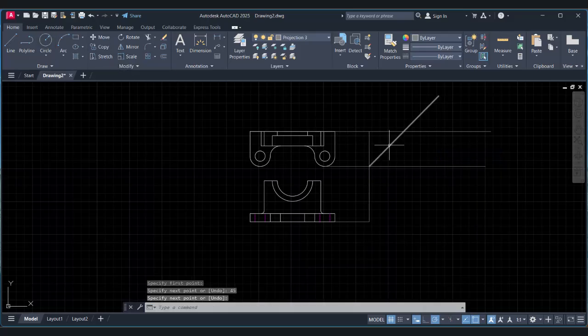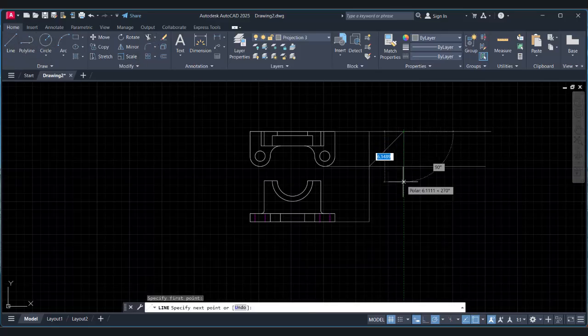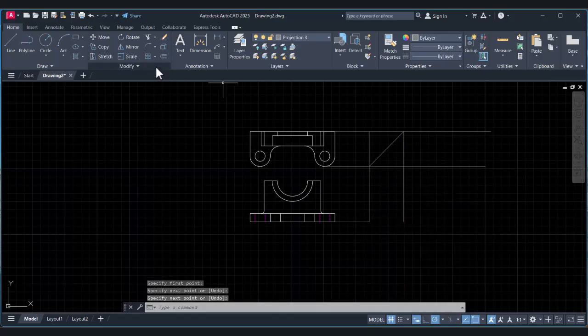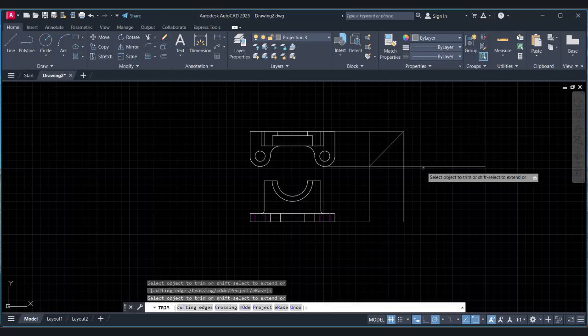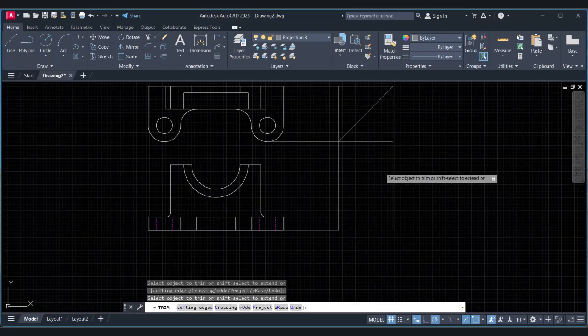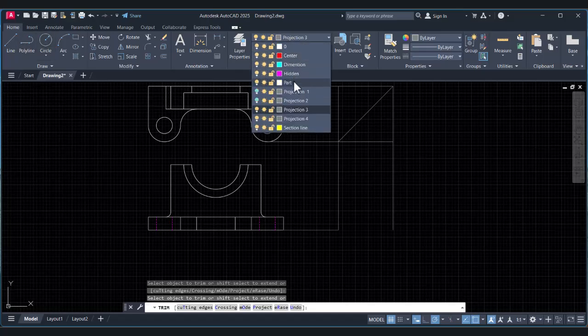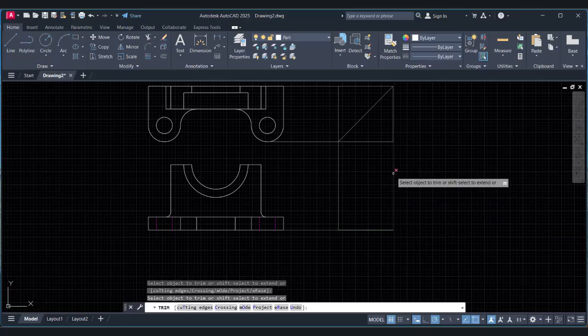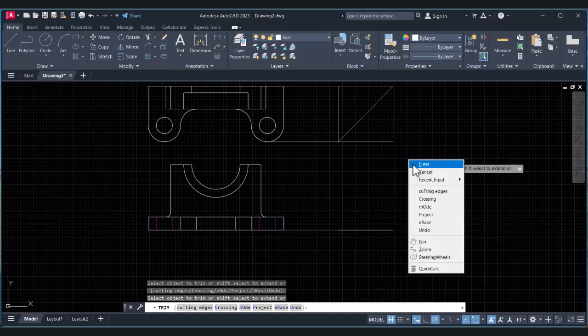So this line is called the miter line, to transfer the right front side view to the right side view. Okay, so then just trim this portion, and I'm going to draw a line till this point like that, and I'm going to trim this portion. Okay, and then I'm going to go to part. So for the part from this point to this point, we are going to draw a line and just trim this point. If you want, you can also trim these lines.